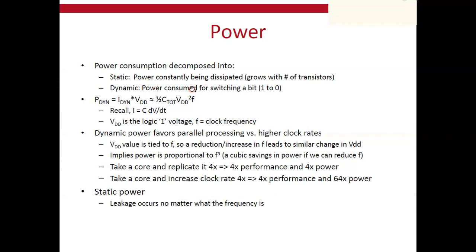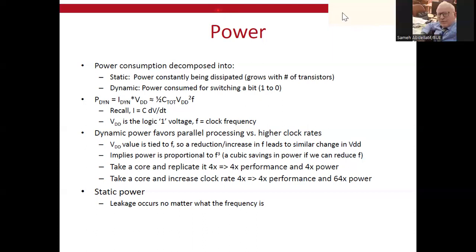So this is very important. VDD, the supply voltage, the total capacitance seen by the chip, and the operating frequency of the clock: these three parameters contribute to the total dynamic power consumed, which is, of course, not preferable to be high in your digital IC design.